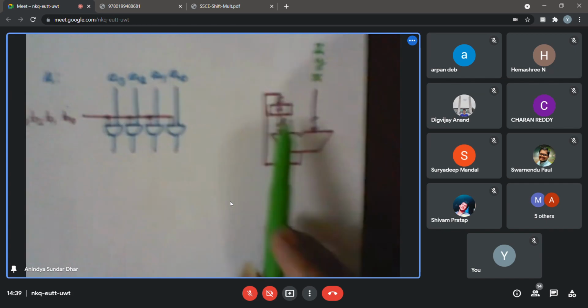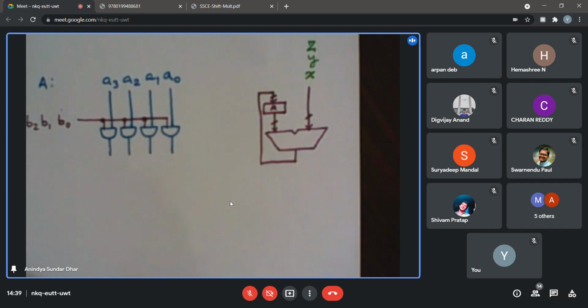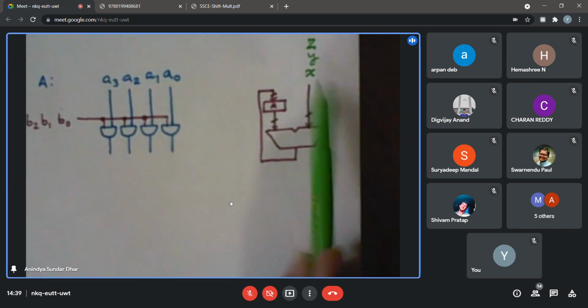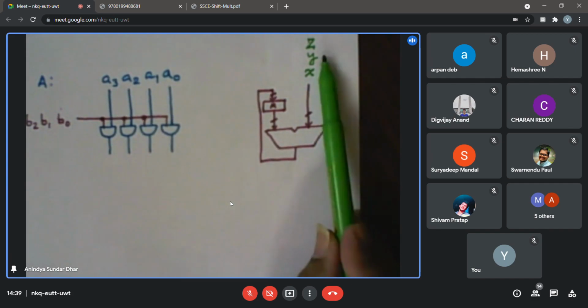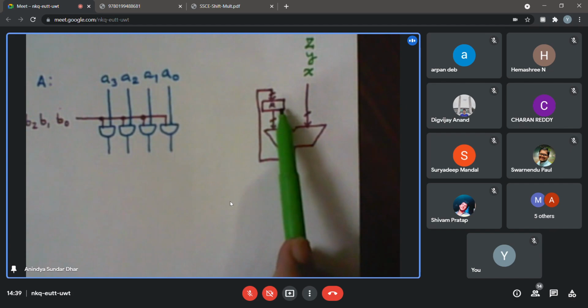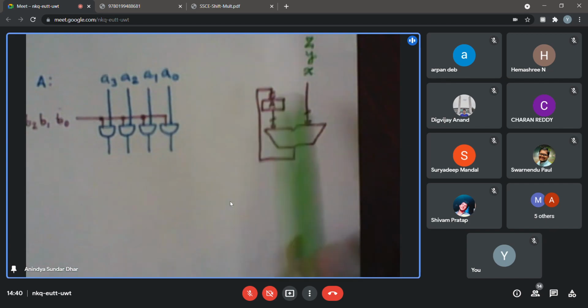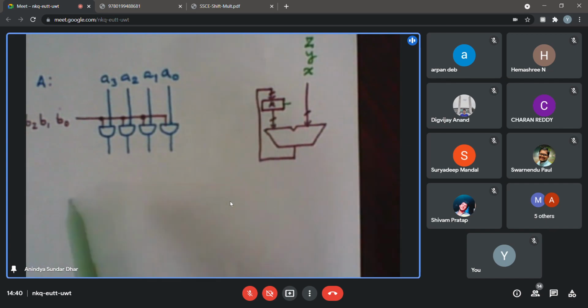Then what will be the final value in this register after those cycles, if sequentially I'm putting X followed by Y and Z? It will be the sum of all those, provided that the register is cleared initially. If it is not cleared, whatever the initial value is will also remain added. So I may assume it has a clear, a clear or reset control.